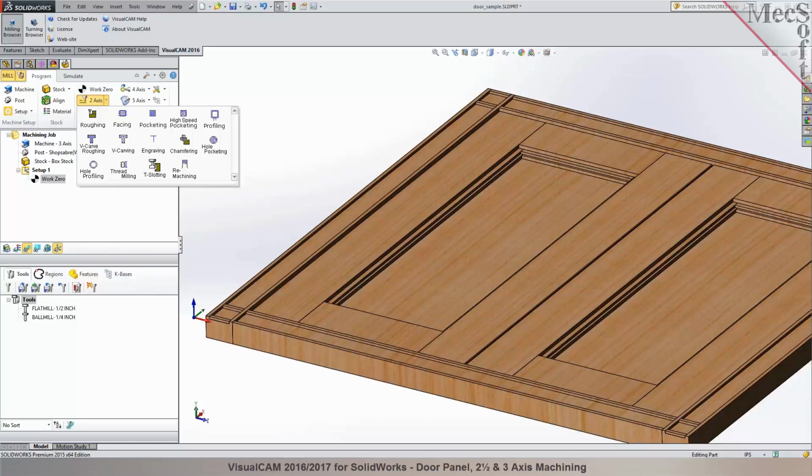Not particularly. Okay. 2-axis milling, also known as 2.5-axis milling, is ideal for parts that are prismatic, which means there aren't any drafts or sculpted bottoms. So the cutter will remain at a constant Z depth as it travels in X and Y, and you can basically step it in levels. That's why it's called 2-axis or 2.5-axis milling.